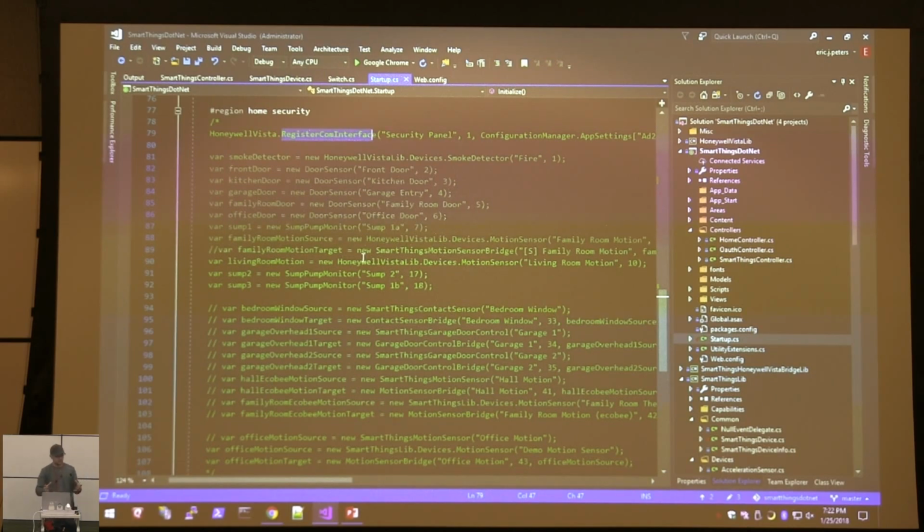The Honeywell device, it's the metal box on the wall. I'm sure you guys have all seen it. You open that up and it's got this big bundle of wires coming in, and it's literally contact switches and normally open, normally closed circuits that just form a loop, and they're resistor terminated. They're supposed to be resistor terminated at the far end, but they terminate them in the box in every instance I've seen, because people are lazy. And so the board itself can sense whether it's opened or closed, or if a wire's been cut, or various different circumstances.